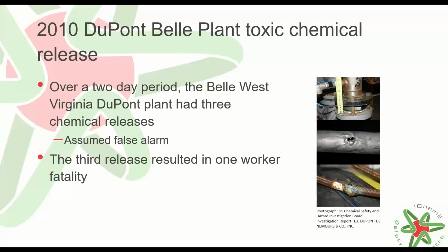And those alarms were very, very unreliable over a period of time. And so the operators had got used to not believing those alarms. They had assumed they were always false. What had actually occurred in the background was some replacement parts had been put in, and the reliability of those alarms improved significantly. So when they saw that they had this alarm, they assumed it was false because they'd become accustomed to it. Again, this is all down to our biases and our normalising what we see. They normalised that that alarm was always false.